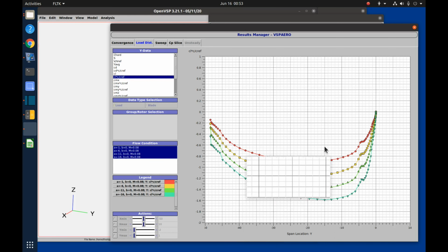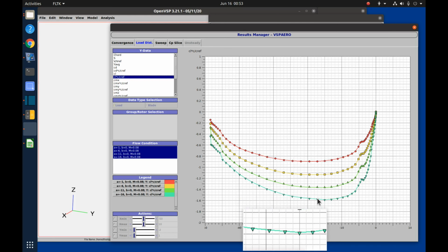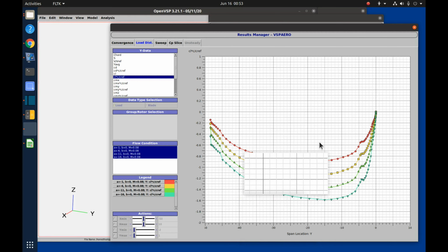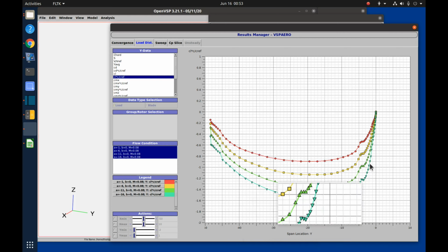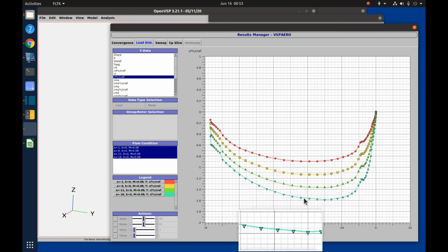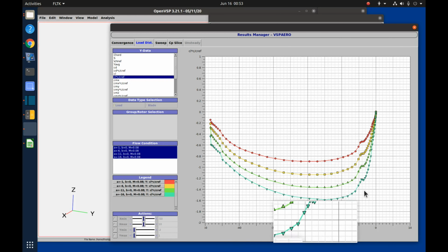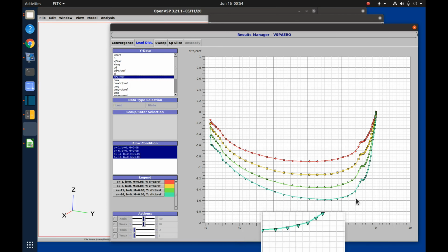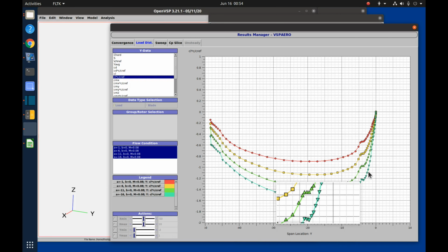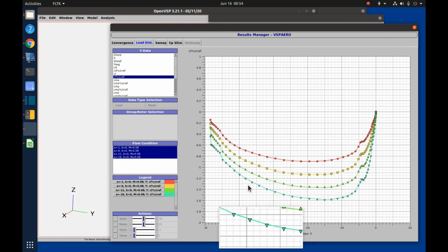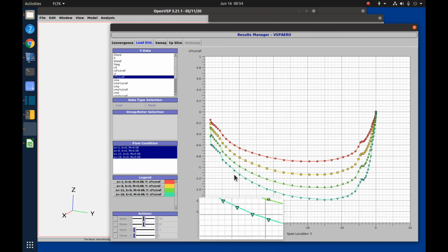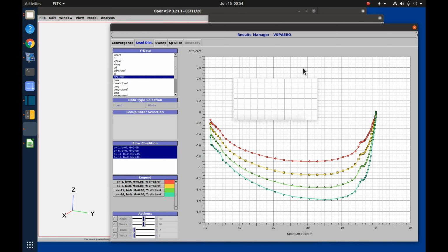So in this orientation, we're getting just a little bit more force from that vertical tail, which is kind of interesting. But the shape looks like it's pretty much the same, but it's possible that peak is a little bit closer to the root. Well, I find that kind of interesting, so I am going to go ahead and use the lift distribution from this negative 16 degrees and from the positive 16 degrees. And we're going to do some comparison on those. Let's go to that now.